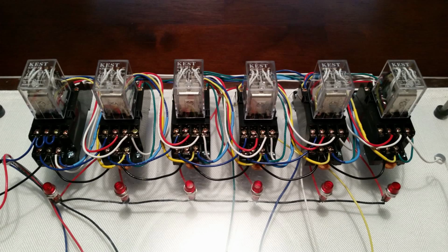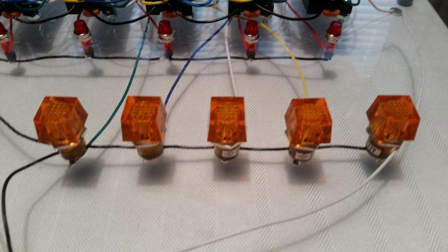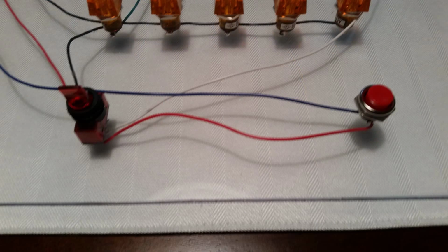With this information, I was ready to attempt a replica of this setup. Using 6 4-pole double-throw relays, I recreated the wiring for the relays JA through JF. To help visualize the relay activity, I added a red lamp to each of the relays to show when it was active. For the 5-wire input system, I used 5 orange lamps to indicate when each bit was active. A red toggle switch is used to set the first bit, and a red push button to simulate the shift register pulses. Let's see this in action.